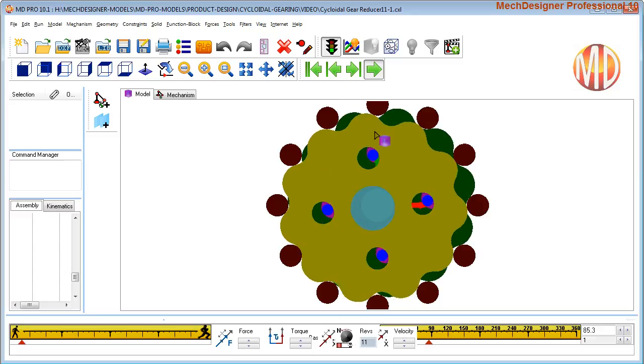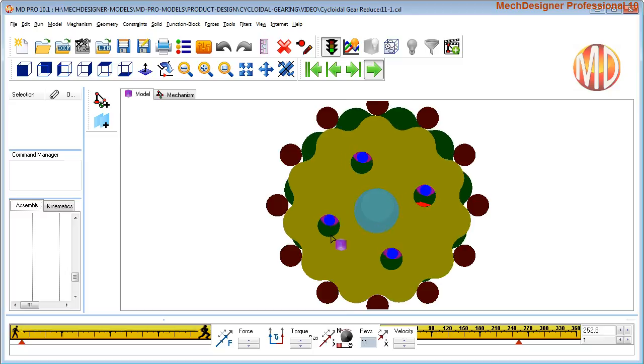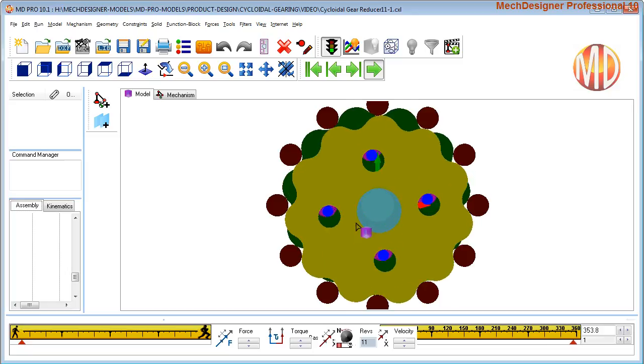Now if you introduce two eccentric wobbling cams, or cycloidal cams, then you can have two sets of holes in the middle of them, and that will, one, balance the mechanism or the gearbox a lot better, so you don't have one disc moving eccentrically.